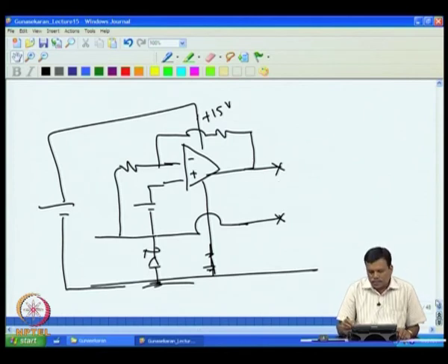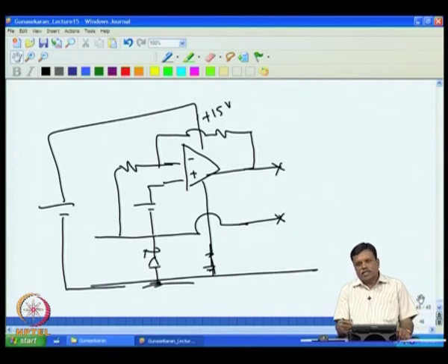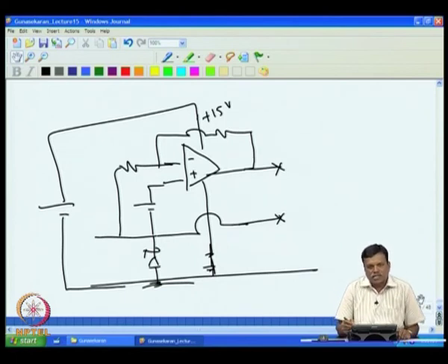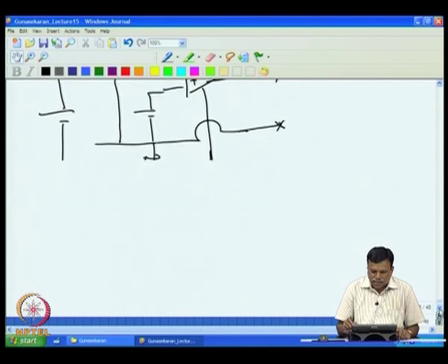So we had seen in the last 2 classes how to make a current transmitter to transmit the signal over a long distance. Current transmitters are used extensively in industry to transmit the signal. As I said initially, this is to avoid noise pickup, because the magnetic field in the loop will induce a voltage, but as long as the frequency response of the current transmitter is good, they will not respond to the magnetic field. So that is why current transmitters are used.